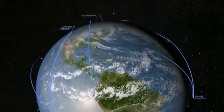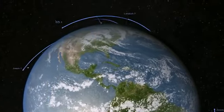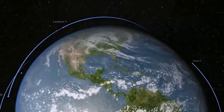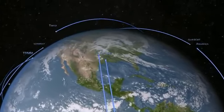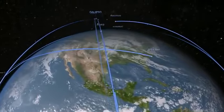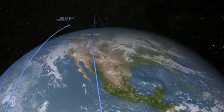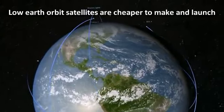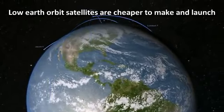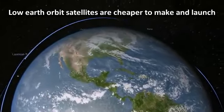Note that not all communication satellites are placed in geostationary orbits. Some are placed in low Earth orbits too. Low Earth orbit satellites can serve the same function, but you have to use many of them as they're moving at such high speeds, and there has to be constant handoff of transmissions from one satellite to another. But the advantage is that these satellites are cheaper to launch and cheaper to make because they don't have to be as powerful, since transmission distances are a lot shorter.